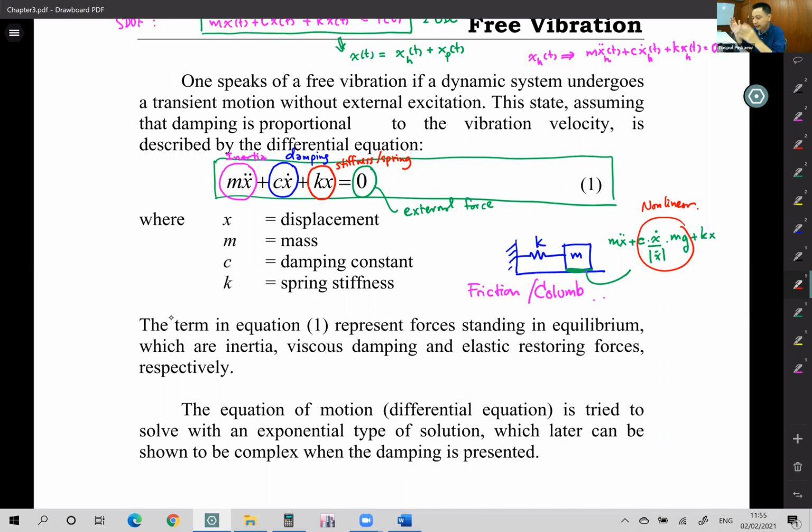Of course, our building damping comes from micro cracks in many parts of the building, in the columns, during the vibrations. We cannot see the cracking like that, but we assume there are some small cracks we cannot see, and that dissipates the energy of vibration. However, to model that, we are looking for the simplest mathematical model to represent the damping term. And the simplest one is this.